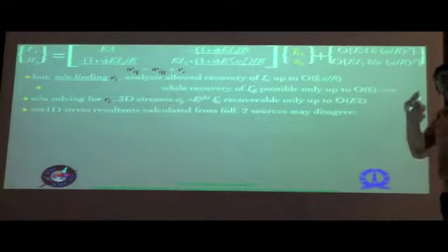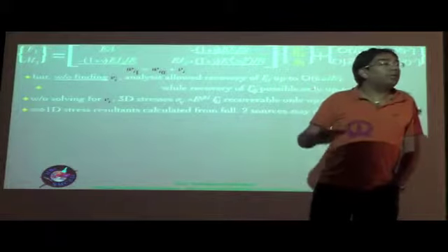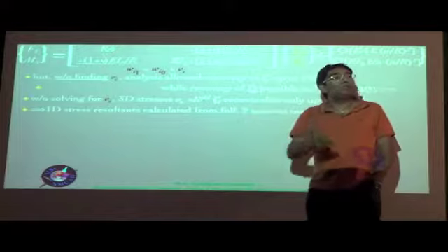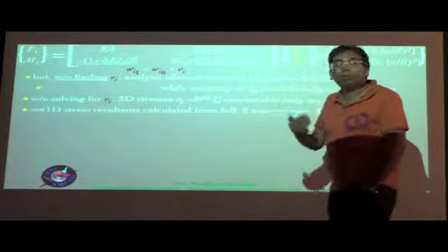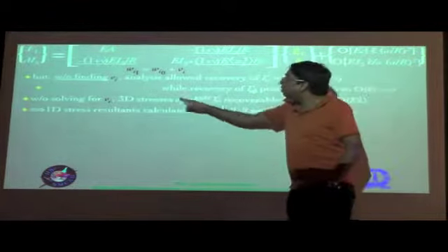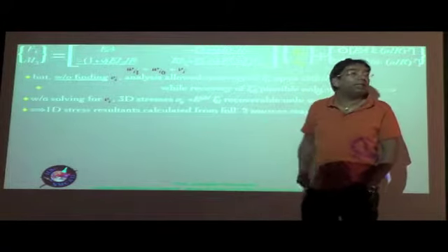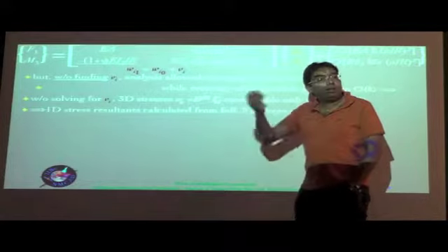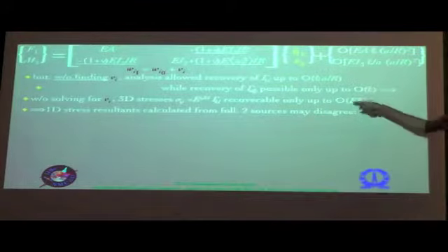The two ways that I talked about: the one which is a more direct way, where you already have the 1D strains, the generalized strains gamma 11 bar, kappa 1 bar, kappa 2 bar and kappa 3 bar, directly substitute that into the 1D constitutive law to get your F1, M1, M2, M3. But instead, if you first determine the sigmas using this relationship and then integrate the sigmas to get the F1, M1, M2, M3, these two in general could disagree because of this confusion or mismatch that we just talked about.